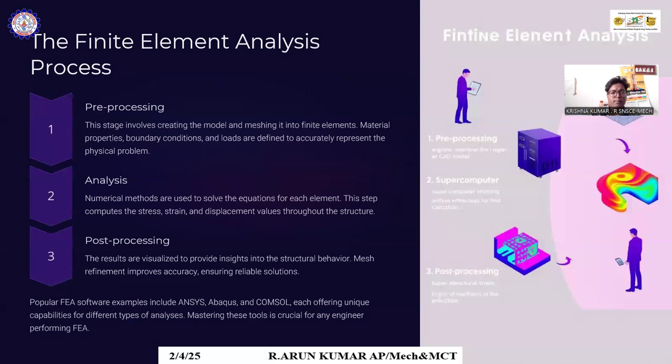Then, what process do I have to follow while doing FEA analysis? Three processes are quite important for analyzing any product. The first is pre-processing, then analysis, then post-processing. In pre-processing, this stage involves creating the model and meshing it into finite elements. Material properties, boundary conditions, and loads are defined to accurately represent the physical problem.